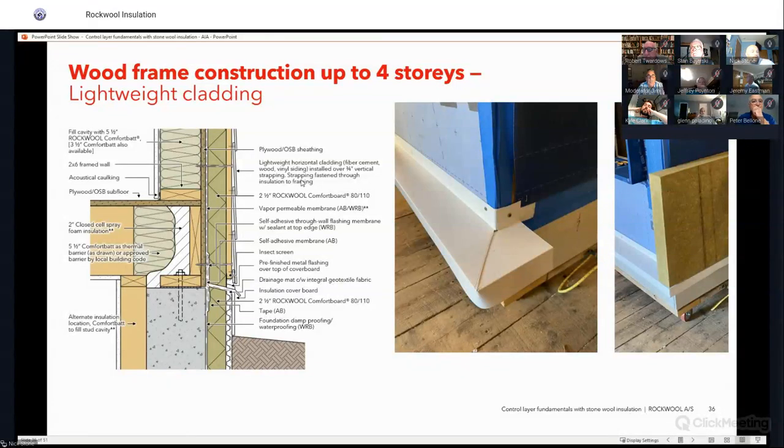So with the new exterior insulation becoming more and more popular, and also just talking a little bit about the cavity insulation, some of the areas to look out for, or just in general talk about, is starting with the outside. When it comes to exterior insulation, continuity is key, and really making sure you have enough from windows to doors to overhangs. Always having that constant continuity.